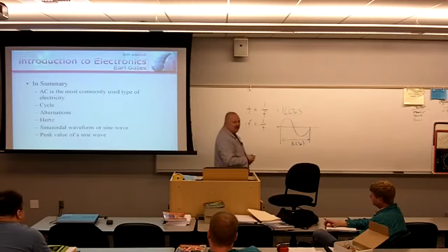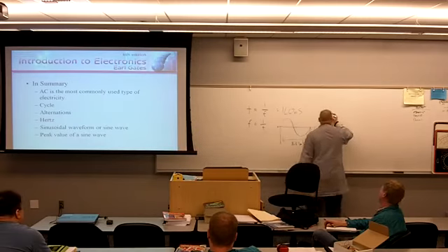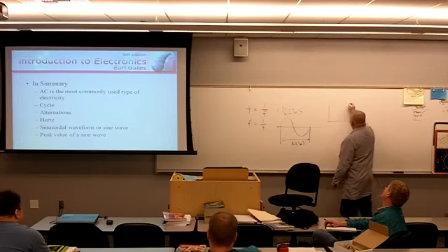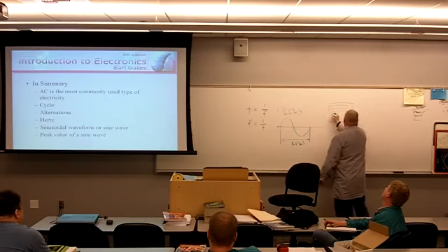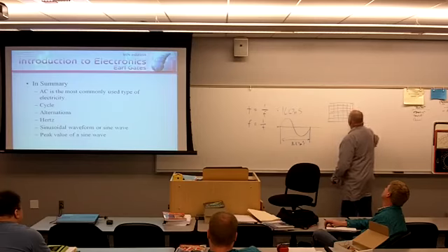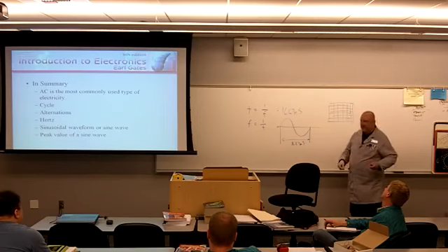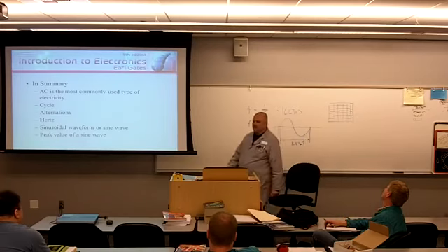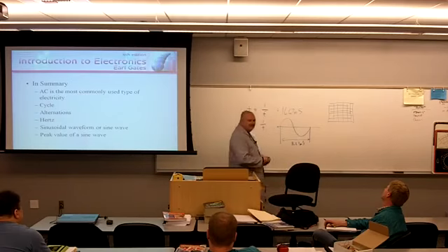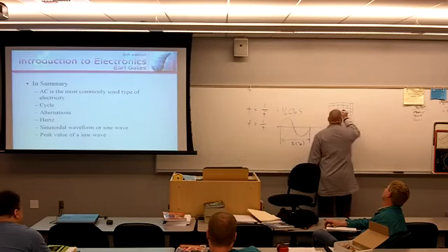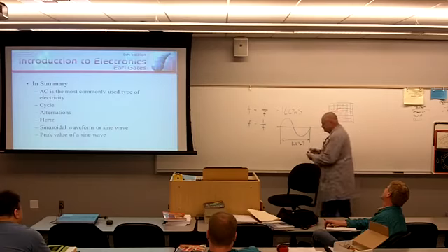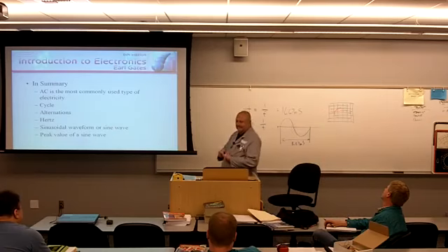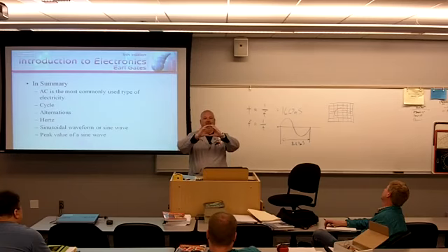And does anybody know what I would come up with on my oscilloscope? There's my oscilloscope face. If I mix those 2 frequencies together, anybody want to take a guess at what I'm going to end up with? I get a circle.